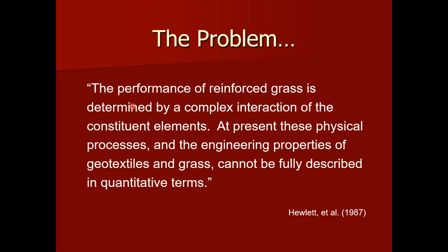It's not a simple rock sizing equation or a block technology where it's a free body diagram of a single particle. We have a lot of interaction between the specific vegetation, the soil type, the type of TRM, the inherent properties of that turf reinforcement mat itself, and the growing seasons. What part of the country the project is in will really dictate what is the native vegetation and how appropriate a vegetated system would be in any given environment.